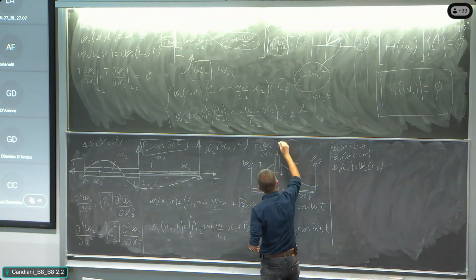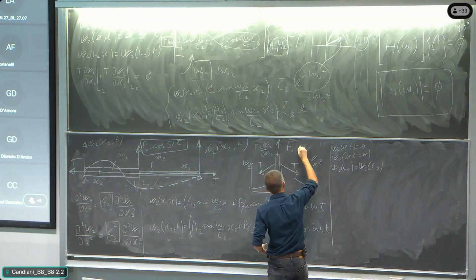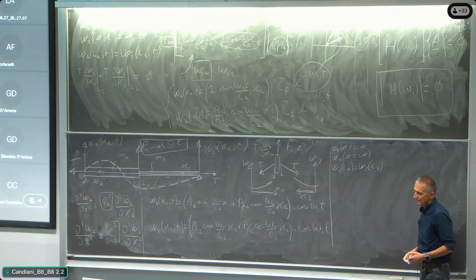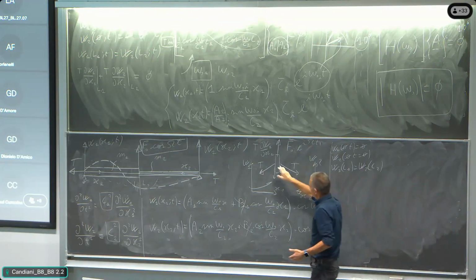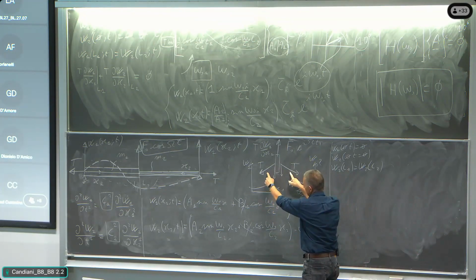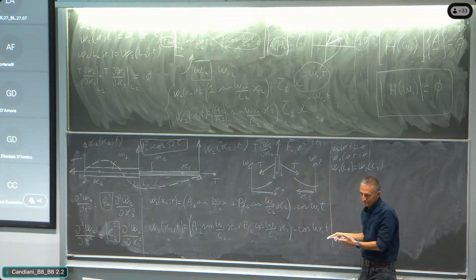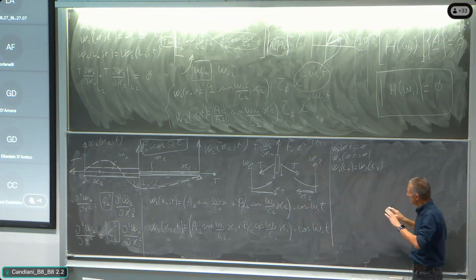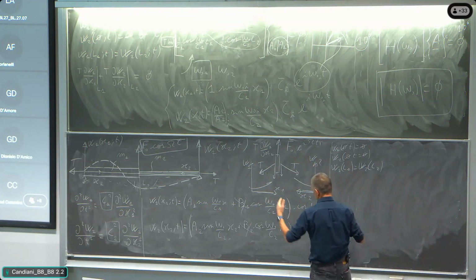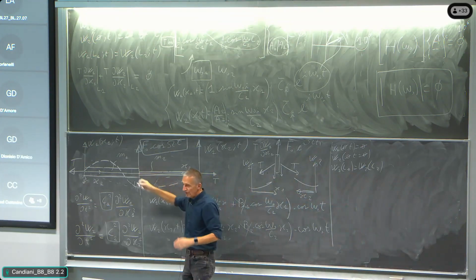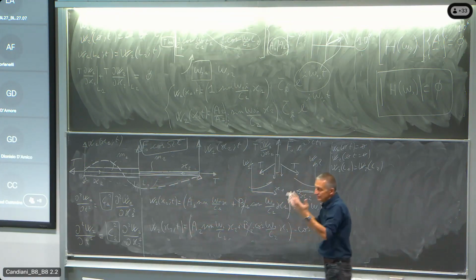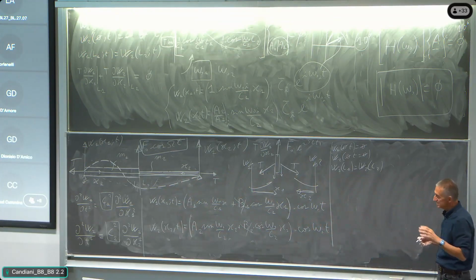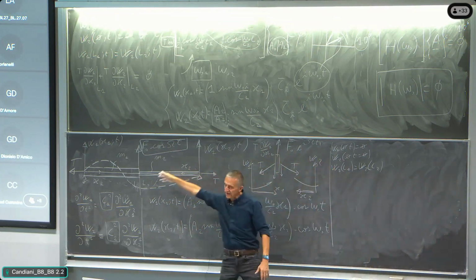Now, if we are pushing here with F0 sinusoidal, we will just say that this plus that is not equal to 0, it is equal to the harmonic force. And so, in order to write the forced problem, we write it as a boundary condition. The excitation force becomes a boundary condition, the boundary condition of the equilibrium at the connection.